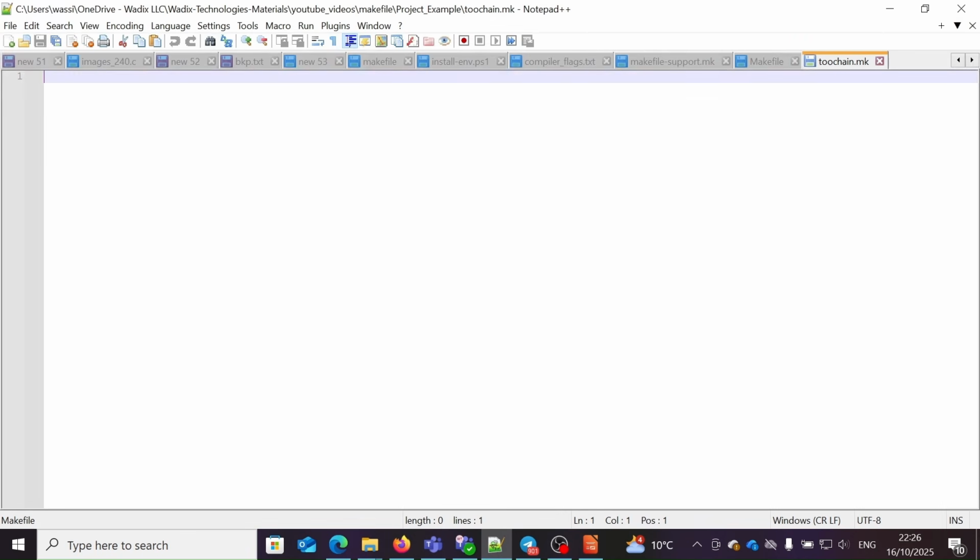I open here. So our compiler will be the ARM GCC. So first of all, I need to identify the top level directory pointing to this ARM compiler. So this will be already our tools, and then it will be under ARM GCC. Then I need the version.